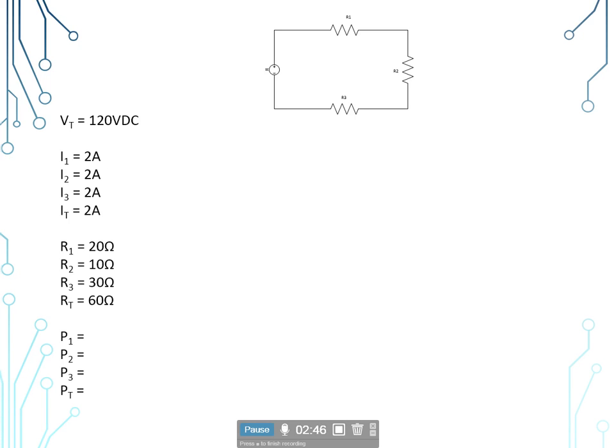To do this, we'll use Ohm's law. V sub 1 is equal to I sub 1 times R sub 1. I know our current remains constant in a series circuit. However, we use a specific current for the component that we're talking about. That way we don't get confused when we switch to a parallel circuit or to a combination series parallel circuit.